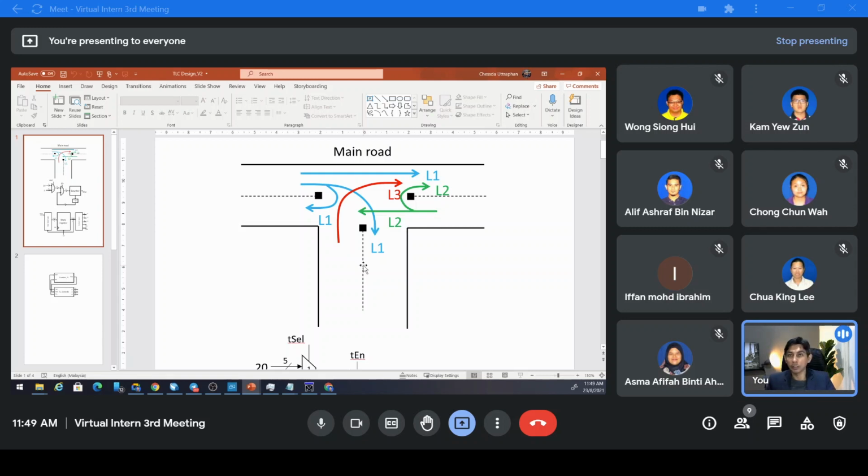But for microcontroller, of course, there is the performance and also the limitation, in terms of the number of I/O and the number of operations that you can perform. So normally microcontroller is not very suitable. For example, Arduino, actually you cannot use it for a traffic light controller in practice, in the real application.